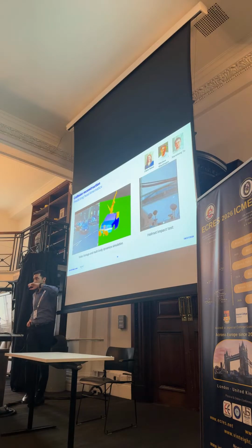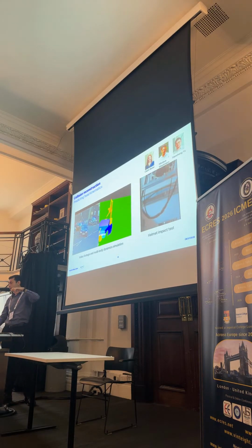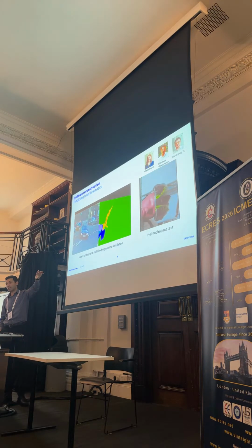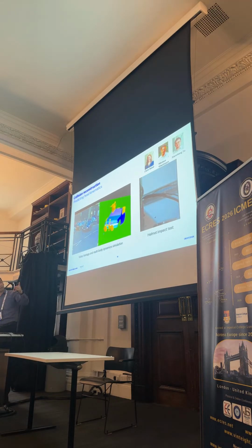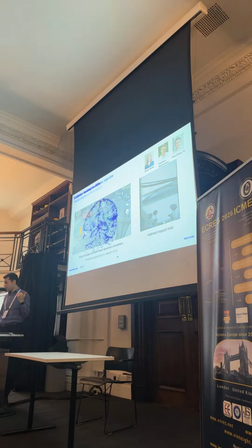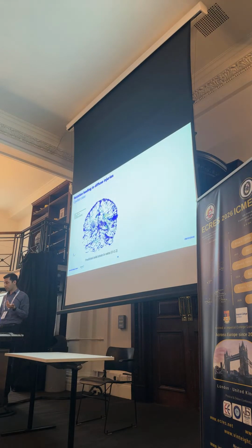And then we used that speed and the location of impact to go into our lab. We have a helmet test rig in our lab, which can test all sorts of different helmets. But in this case, we tested cycle helmets with a Hybrid III headform, with accelerometers within the headform. So we measured the kinematics from that, and then we applied the kinematics to our brain model.